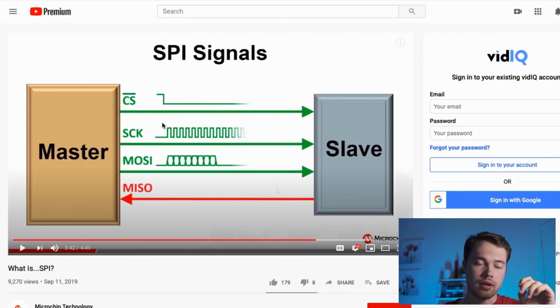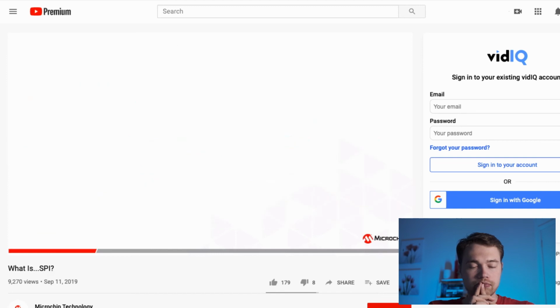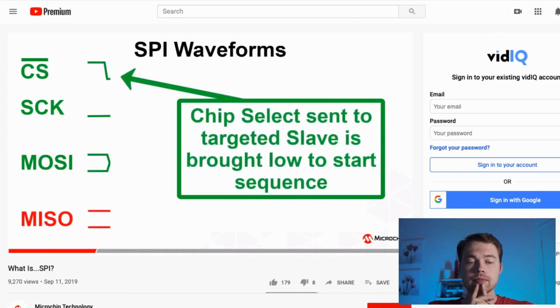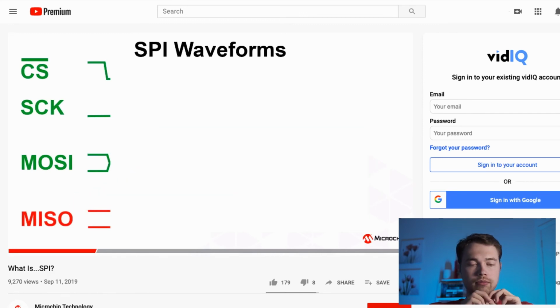So these 3 green signals are generated by the master. They go from master to the slave, and this red wire is the signal generated by the slave, and the master is just listening to it. And the bottom signal MISO is generated by the slave that is selected. To start an SPI transaction, the master must select the slave device by asserting CS or driving CS low. This tells the specific slave to listen for an SPI command, also called an opcode.